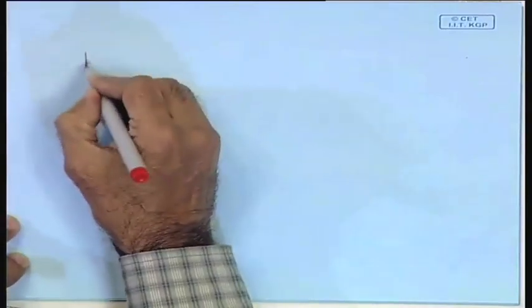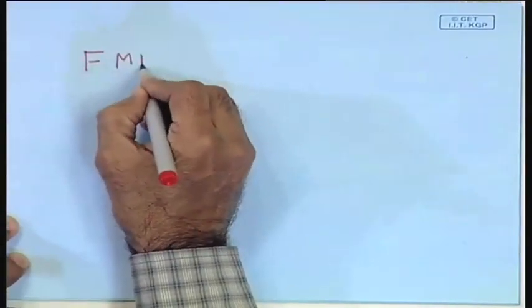This is where we have to actually ask the question, how would this fail? How could this design fail, for example? If I've got a simple product here, I've got a pen in my hand. In what different ways could this pen stop working? That is the question I have to ask, and I have to construct this engineering worksheet, and that is called the FMEA, Failure Mode and Effects Analysis worksheet. So that worksheet will be called an FMEA worksheet.